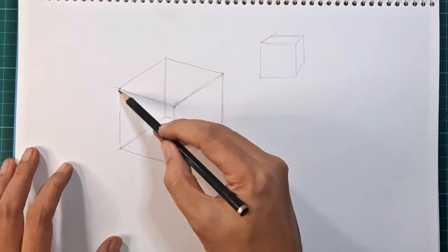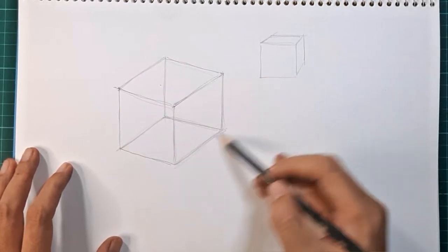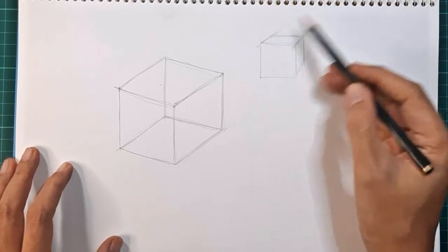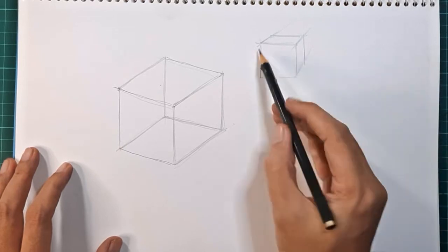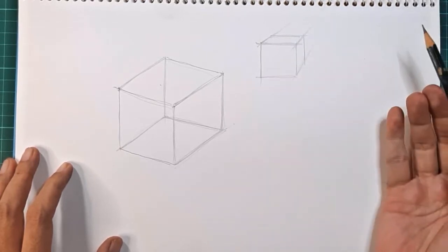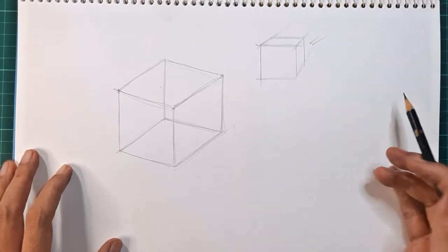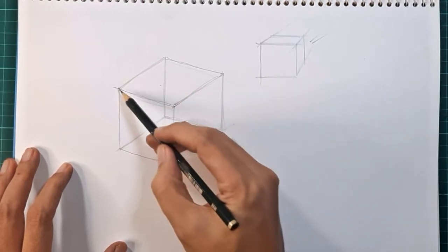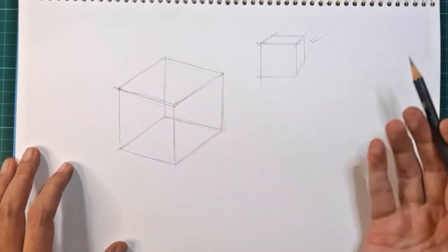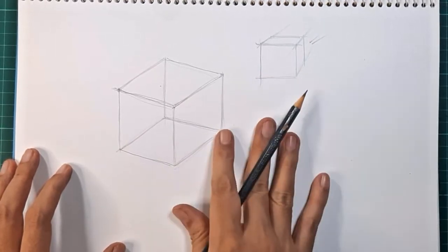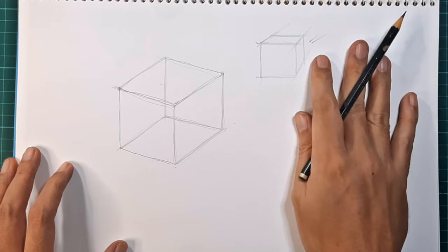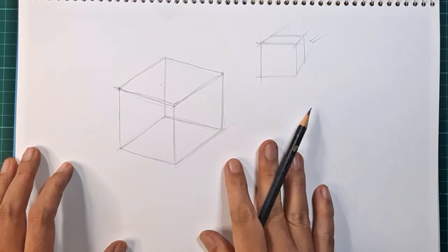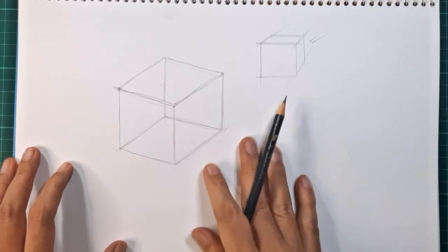In the axonometric drawing, the lines are essentially parallel, but in a perspective drawing, there will be some lines that won't be parallel to each other depending on the view that you're using. We will be tackling perspective drawing in the next section of this course. For now, in 3D drawing, we'll be starting with axonometric drawings so that you'll be able to grasp the concepts. The concepts in 3D drawing will be applicable to perspective drawing, like what you did in the box slicing drill, in the box with cylinders drill, in the building blocks drill.